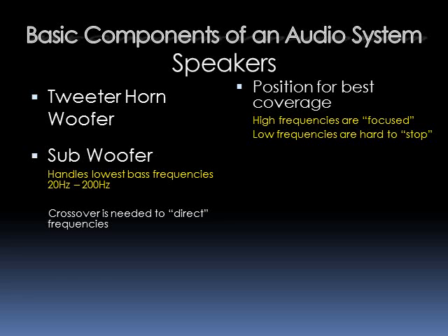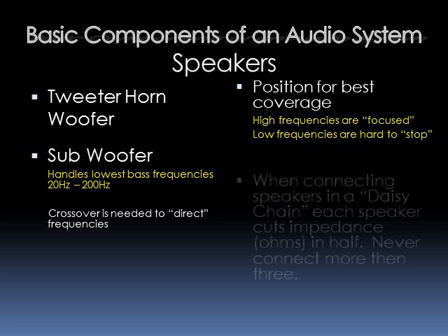A subwoofer or even a woofer reproducing a big, long, low frequency sound wave can't even really reproduce something that's very short and very high. But if you run the full signal to each one, it's going to try, and you're going to burn up the speaker.